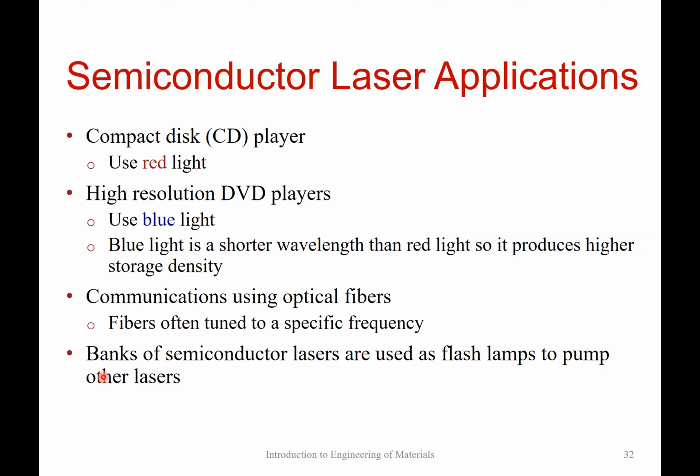So there's that. And in terms of lasers that we experience every day, obviously there's lab grade, there's industry grade, where it's very high power for laser shock peening to induce compressive stresses so that you can strengthen the material at the surface. There's also everyday lasers that we experience, right? We use red laser pointers. So that's just generating a red laser, and it's very low power. It's like milliwatts so that you don't burn your eyes.